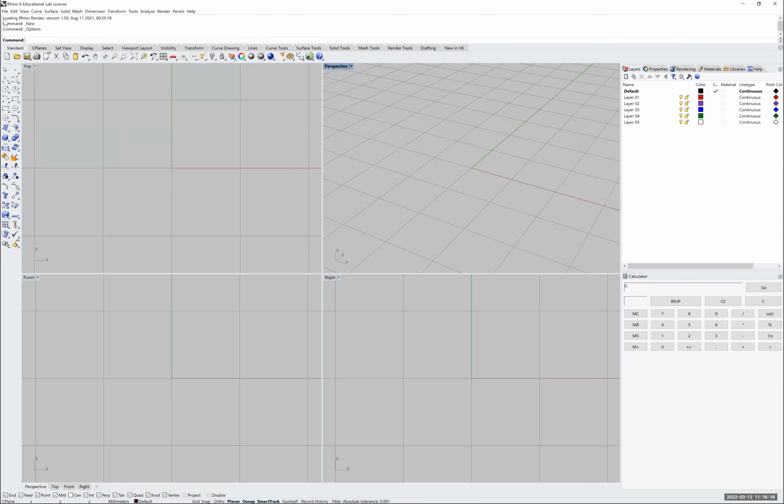If we go slightly downwards towards what we call the command line, now similar to AutoCAD, Rhino works with command lines. Right now I have a history of the latest 3 commands that were introduced into my document. Obviously, I've just opened the document and therefore my commands are limited. Below that, I have this little line that says command, and it's waiting for me to enter the command. And this is where I can start typing.